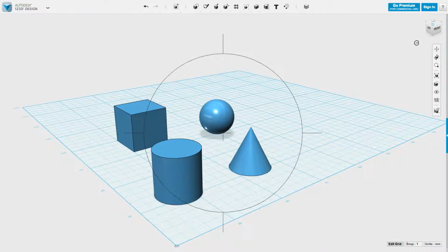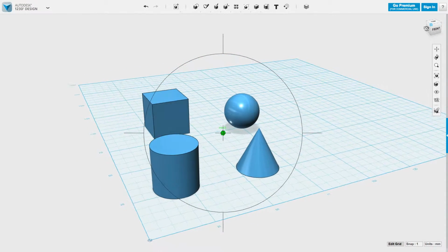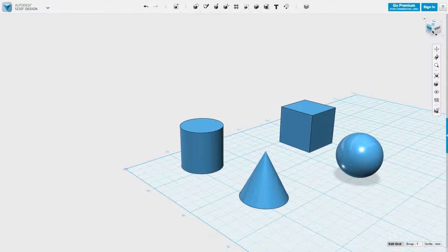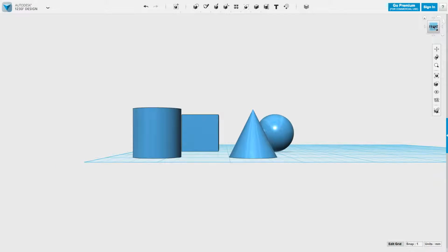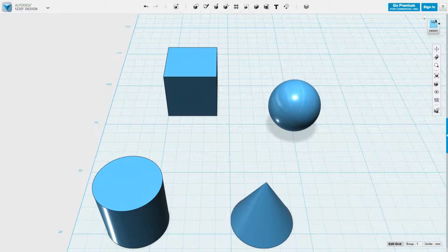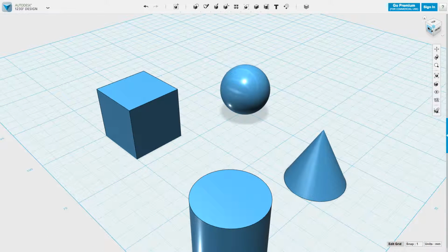Also, as a shortcut, you can click on this little cube in the top right hand corner and drag out and in, and that'll also rotate it. If you want the front view, you just click on the front, top view, click on the arrow above the front. If you want a dual view, click on the segment that matches the top and front, or whichever two sides you're looking for. Same thing with the corners, you can get 3 different planes that way as well.